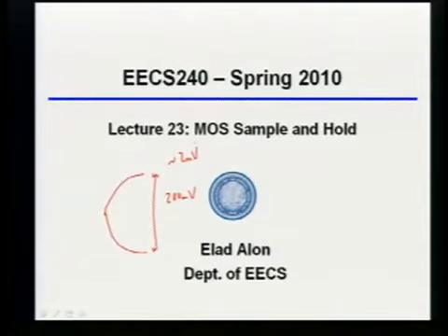In like 1% final value. Exactly. So if you're using a 1 volt swing, that would mean within 10 millivolts. If you're using a 200 millivolt swing, which is probably what I gave for the default at the output of that CML comparator, 2 millivolts is what you need to settle to within. Other questions on the project?